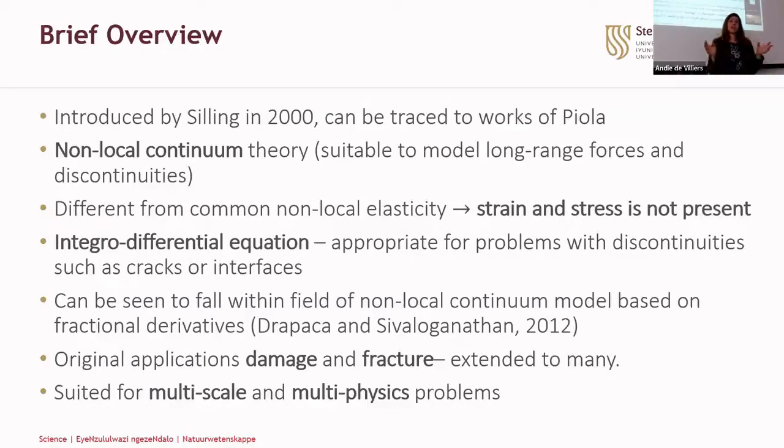But the peridynamics formulation is an integral differential equation, or the governing equations are written as an integral differential equation. So it's appropriate for problems with discontinuities such as cracks and interfaces. And so it's not really surprising that the applications that use peridynamics to model damage and fracture have grown exponentially in the last 2 decades. But there are also other applications, and it's suited for multiphysics and multi-scale problems.